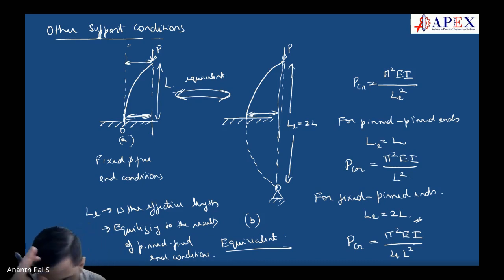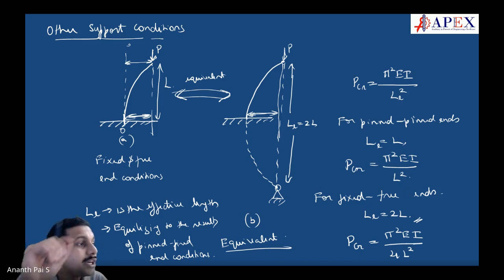So that is free end. Okay, I'm sorry. This is free end, not a pinned joint. Fixed, sorry, so this is wrong. Fixed free end. I'm very sorry, students. Change this one. Fixed free end. Very important. Pinned is different. Free is different. Pinned means it's not allowing to move in the horizontal direction. Free means it can move in the horizontal direction.